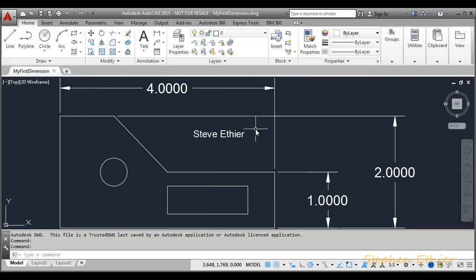To make sure you're getting everything that you have drawn onto your layout, always use the zoom extents before you plot. Sometimes objects get drawn way out in drawing outer space, or in this case, outer model space, and you don't realize until you plot your drawing onto paper and everything is offset or too small and there's something very tiny in one corner of the sheet, the elusive outer space object.